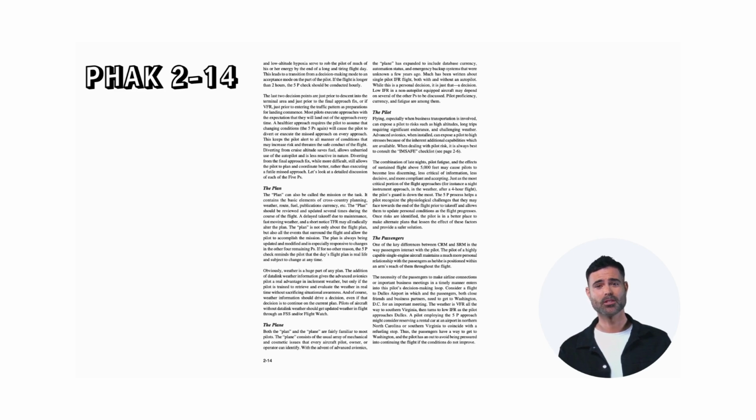The last 2 decision points are just prior to descent into the terminal area and just prior to the final approach fix, or for VFR, just prior to entering the traffic pattern as preparations for landing commence. Most pilots execute approaches with the expectation that they will land out of the approach every time. A healthier approach requires the pilot to assume that changing conditions, the 5 Ps again, will cause the pilot to divert or execute the missed approach on every approach.